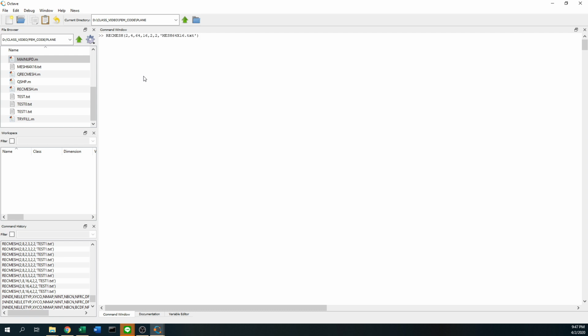Yeah, the 2 here, I didn't think much at the very beginning. So 2 now, if it turns out to be 2 centimeters, what is good? 2 centimeters multiplied by 64 discretization, then we end up with 128 centimeters, which is just a 1.28 meter beam. That is stupid, right? So I think, well, as it is a beam, just make it longer. How to make it longer? Make it 4 centimeters, turns out to be just a 2 meter beam.